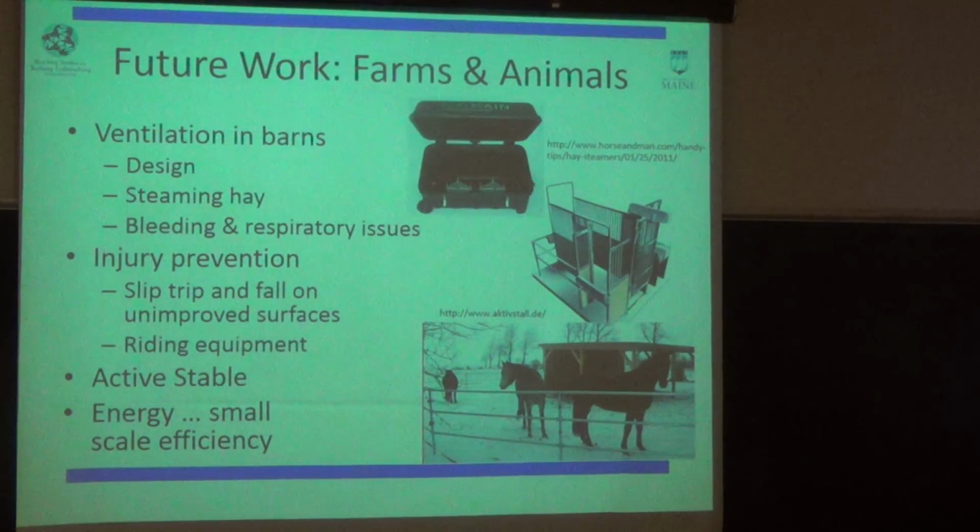Some of the things that have become just huge in the industry is Bill Kasner at the Welfare and Safety Summit gave an impassioned talk about ventilation in barns. It's oftentimes a design issue. You're bringing the air in from the bottom, maximizing the airflow from the bottom, taking it out the top. If you've got dust on the bottom that's coming from feed, what are you doing? You're maximizing the amount of dust and particulate matter that's aspirated by the horse.